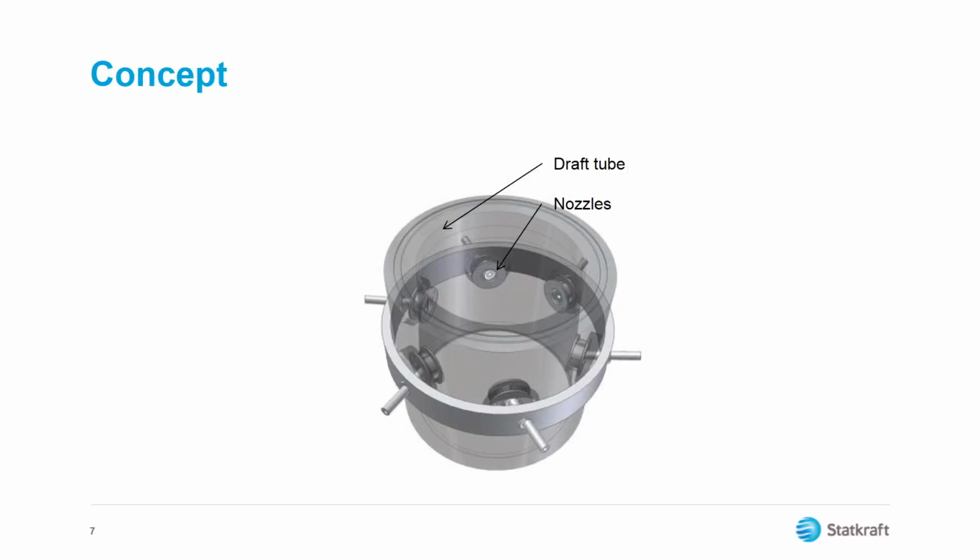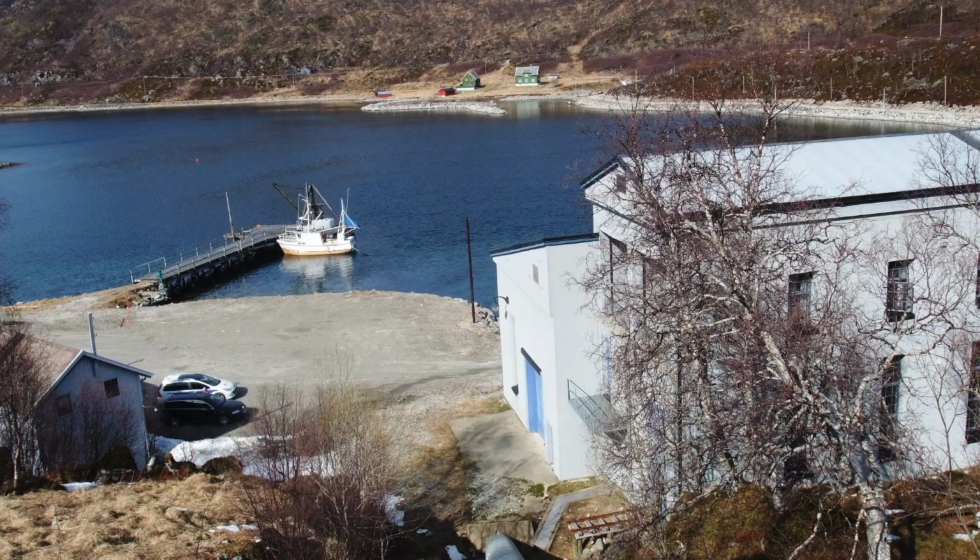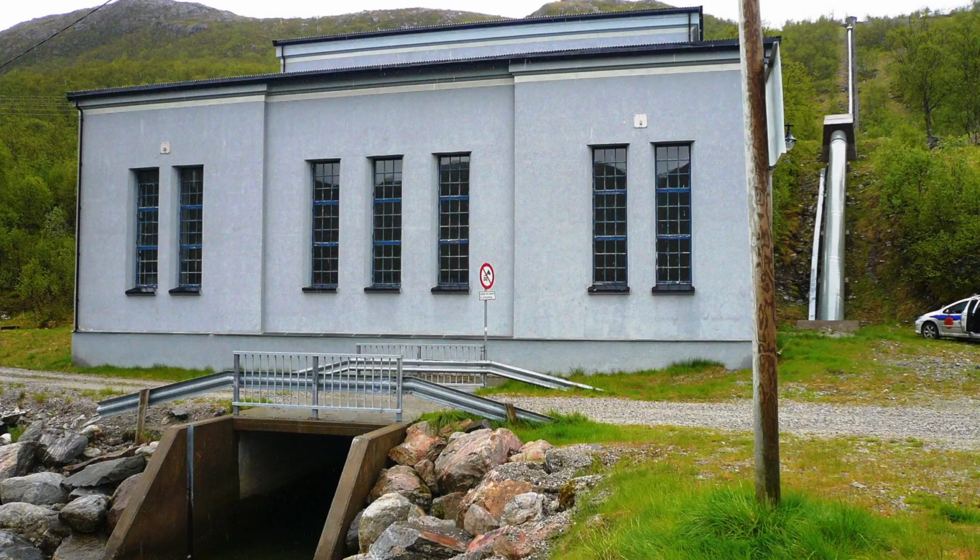The idea of the injection system, as the name implies, is to inject water in the opposite direction of the spin. This reduces the rotational energy and improves the flow through the draft tube. Ultimately, this should hinder the birth of heavy part load pressure pulsations. The system was tested out on 2 of Statkraft's power plants with good results.